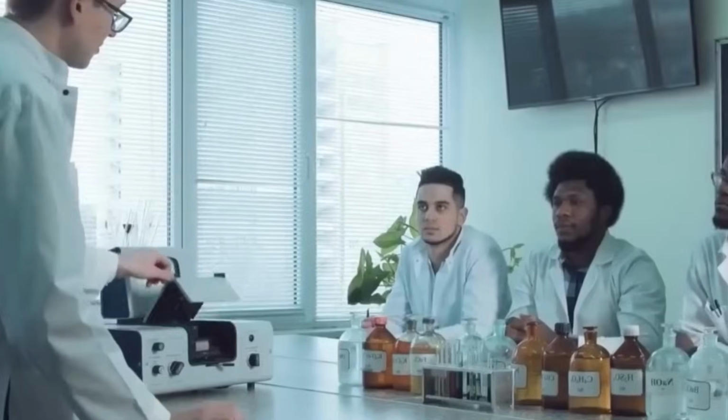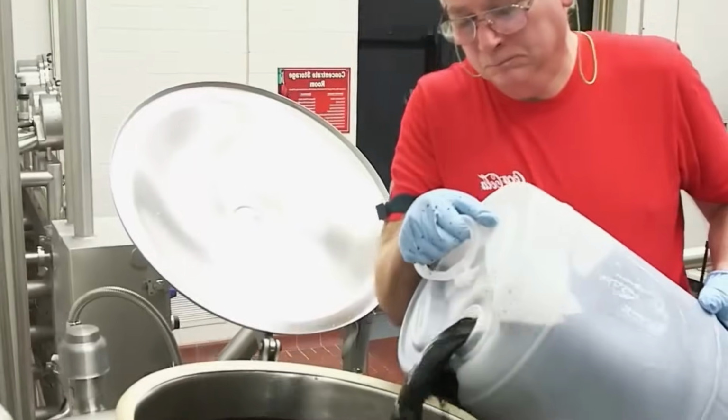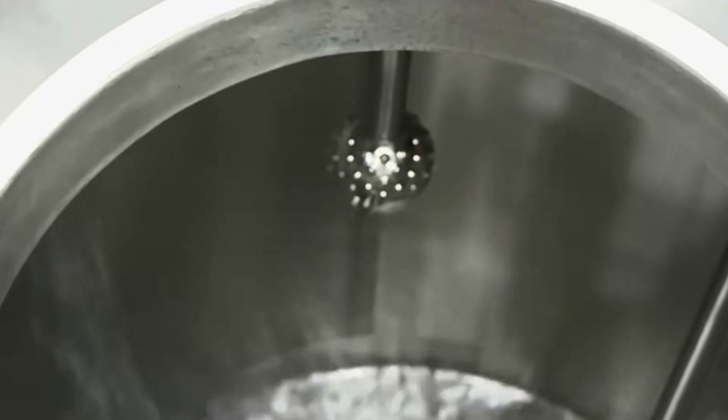Immediately after filling, containers proceed to the capping station. In bottle lines, caps are sorted and oriented using centrifugal feeders. Each cap is dropped into position and pressed onto the bottle using pneumatic or servo-controlled spindles. Torque sensors ensure proper seal strength. For cans, lids are fed through chutes and placed atop the can mouth. A seaming head engages, folding and curling the lid's edge around the can's rim to create a hermetic seal. The container is then released to a discharge conveyor.